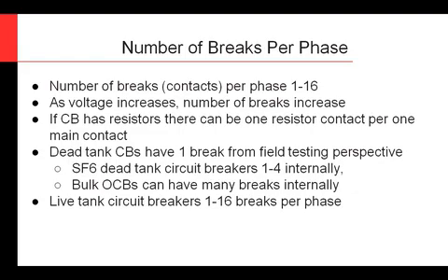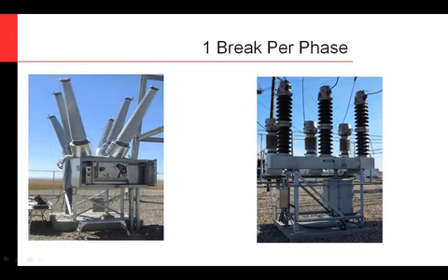Live tank circuit breakers, on the other hand, you get to see how many breaks they have right there in the field, and you can test each break individually and hook up to them. So here's an example. On the left, we have a dead tank circuit breaker. You have your 3 phases, and the tanks are kind of hidden by the cabinet, but your 3 interrupters are there. And that's 1 break per phase.